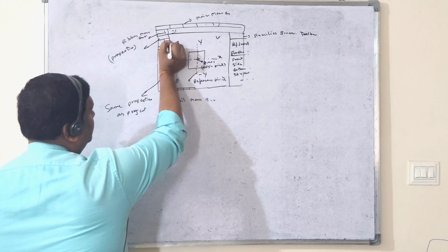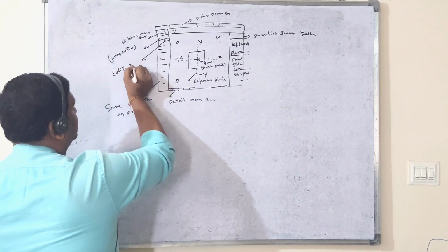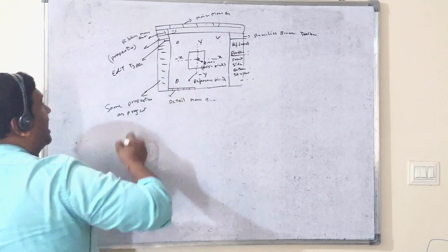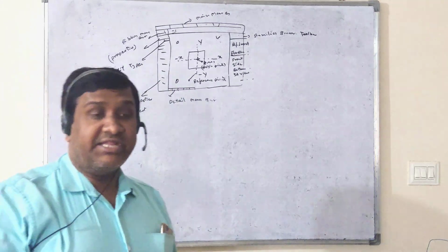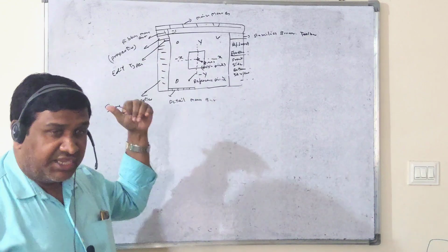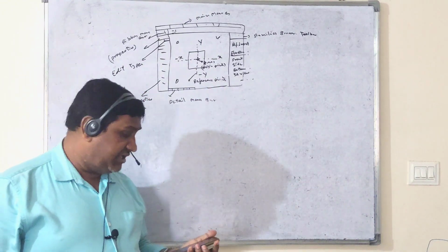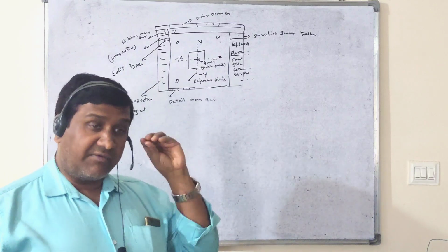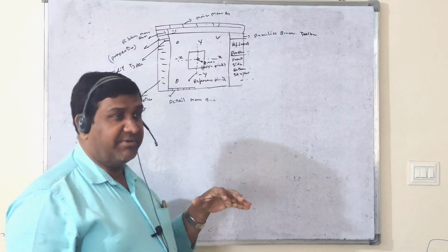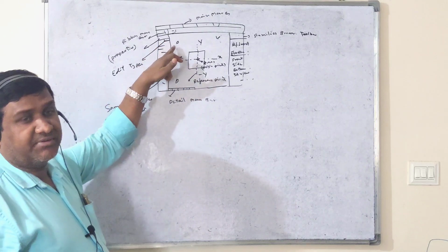But here one more menu is also there, Edit Type. This Edit Type menu is very important, because I already told you that parameters are of two types: instance and type. When we create any family we have to give some parameters, and those parameters will become instance or type.